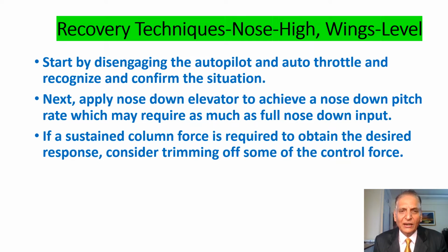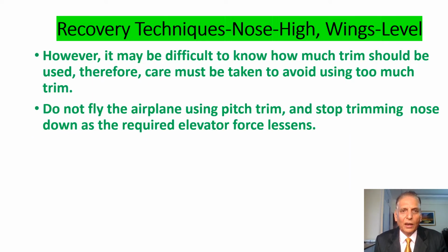If a sustained column force is required to obtain the desired response, consider trimming off some of the control force. However, it may be difficult to know how much trim should be used. Therefore, care must be taken to avoid using too much trim.